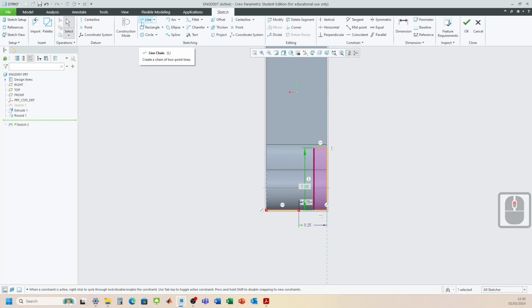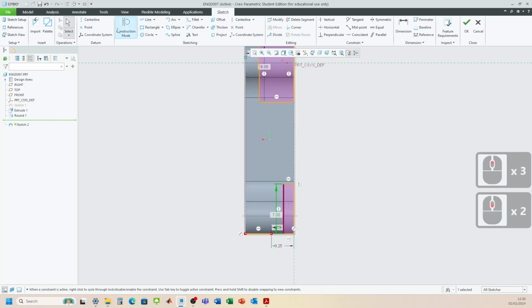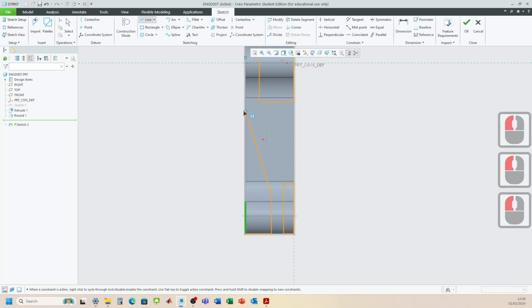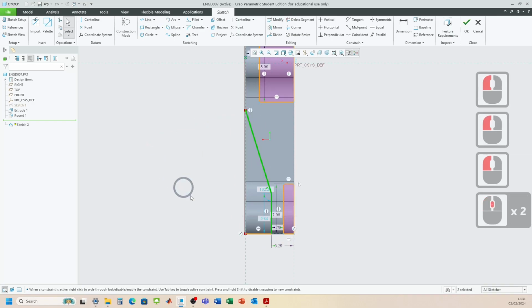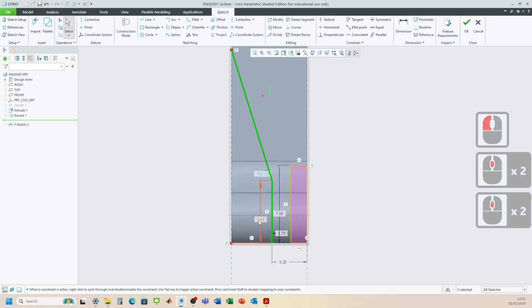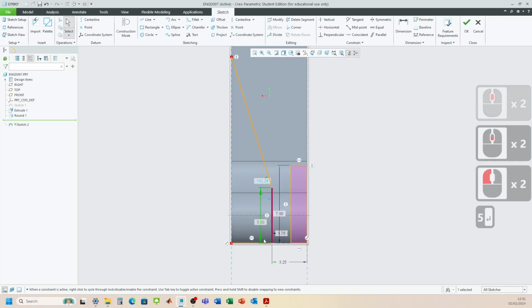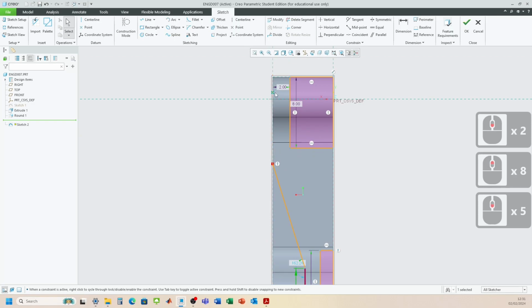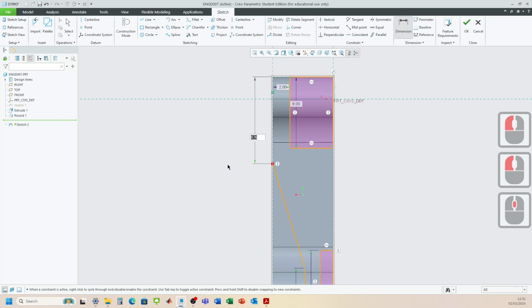And then what have we got here? So we've got 5, and then it goes to 10.5 there. Okay, I'm going to go here, and then there like that. So we need to make sure we dimension this up correctly. So this is going to be 5. You see, this is getting its distance from the angle at the moment, but from the drawing, we know the distance from there to there. So I'm going to add a dimension in. So there to there to there. So that's 10.5.